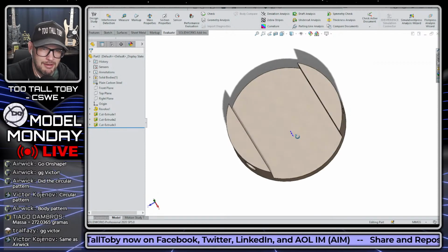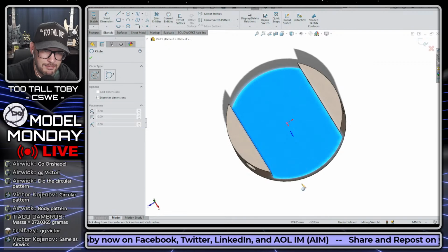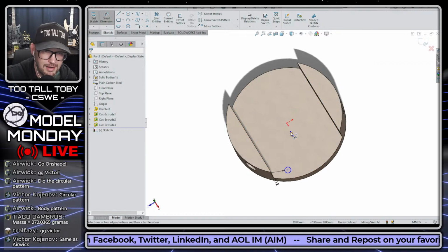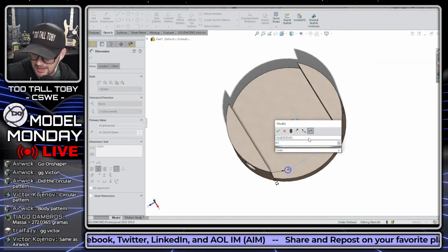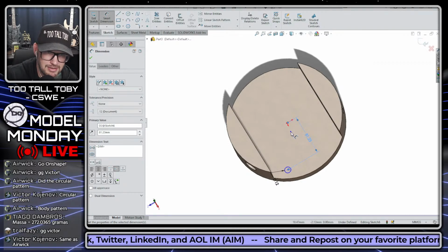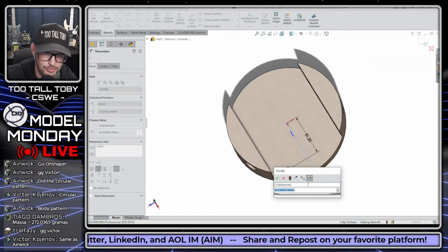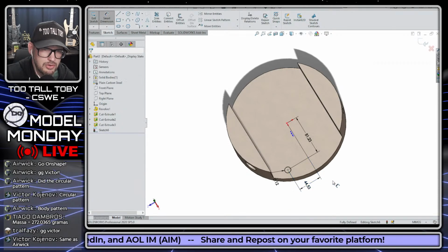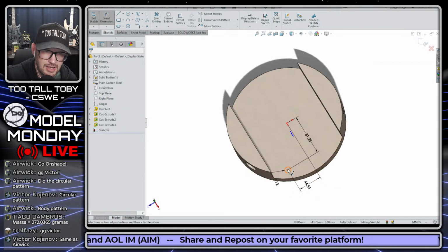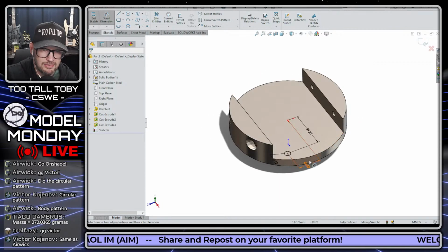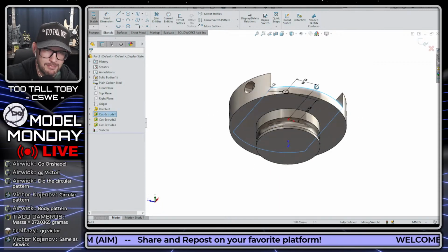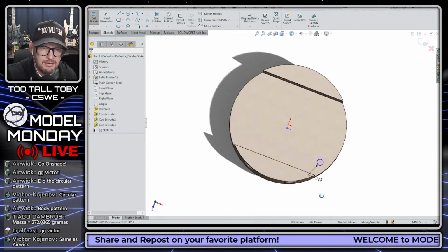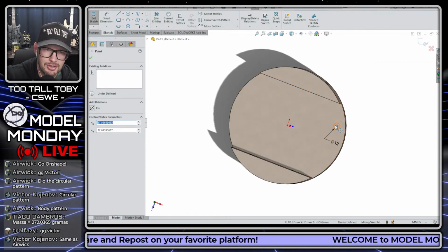Basically, if there is a hole here on the outside of the model and it's meticulously defined as far as the location of that hole, so if it's at a dimension here of like 81.23, and a dimension over here of something kind of annoyingly defined, like 44.5321 or something, you don't actually have to worry about defining the location of that hole, because the mass that will be removed from this model when you go from this face to this face will be the same regardless of where that hole is.